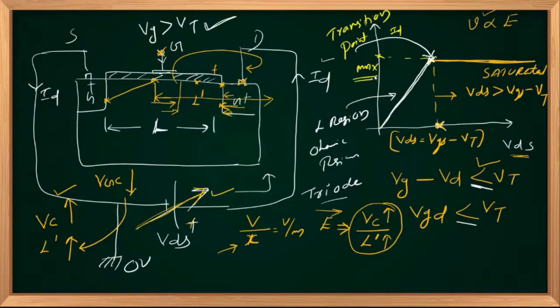And you should not confuse. This curve is plotted for a value of VGS greater than VT as we assumed, and that is VGS1, one particular value of VGS. If you plot the same curve, you will have a plenty of family of curves based on different VGS values. If you have a different VGS greater than VGS1, you will have a curve like this. That is VGS2. Please don't confuse. There is an individual curve for an individual VGS.